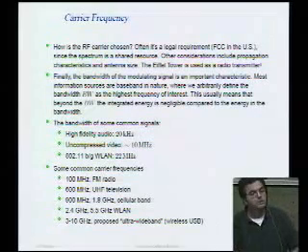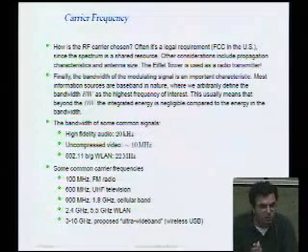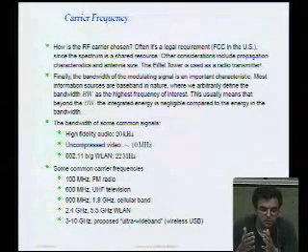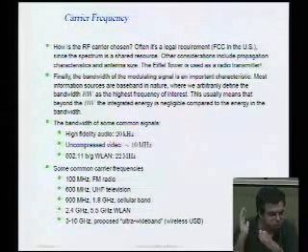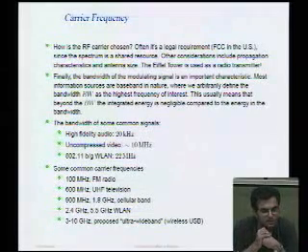Now the other constraint that we already touched upon a little bit is bandwidth. Depending on what kind of information you're transmitting, you have to also take into account how much bandwidth you're going to occupy. So in other words, if I'm going to transmit voice at 1 gigahertz, I may only need about 10 kilohertz of bandwidth. Maybe 100 kilohertz if I want to transmit FM.